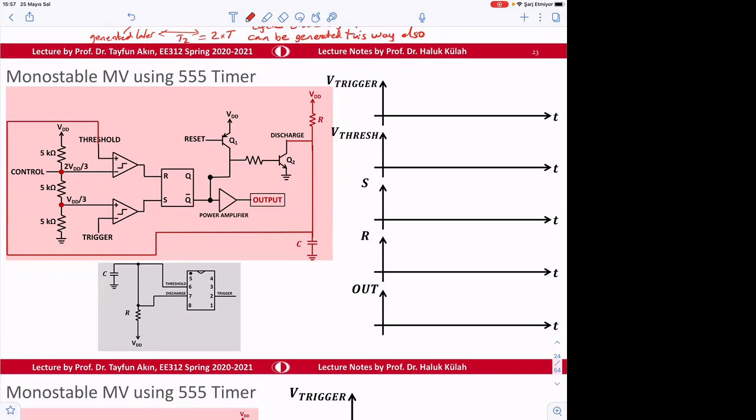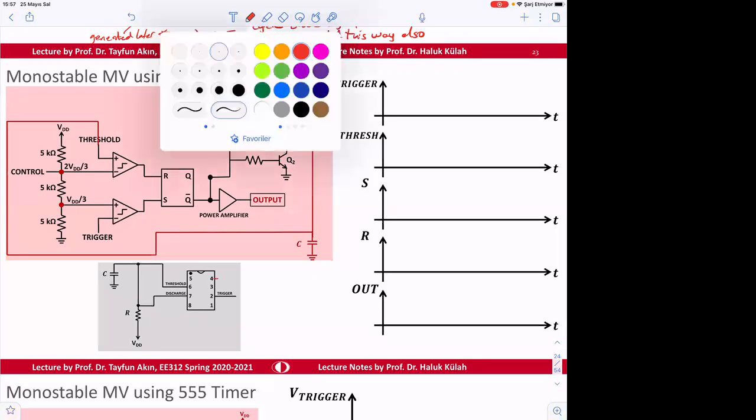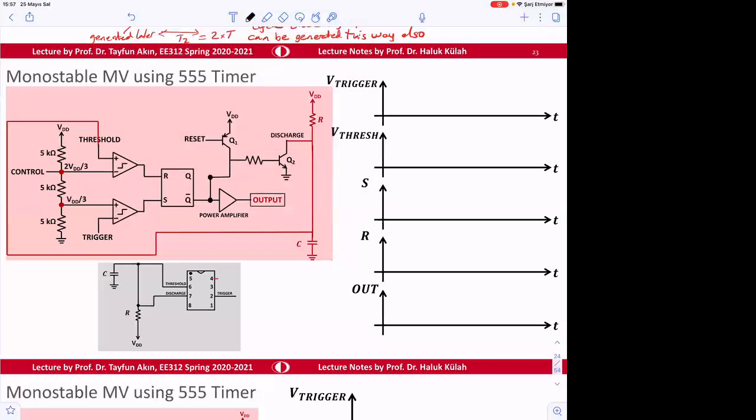So that was the case. Here, in order to make this circuit operational, we connect VDD to reset. This was reset, so we set this thing to VDD, so this becomes off. That reset signal, we don't need it for this circuit, so we turn that off.